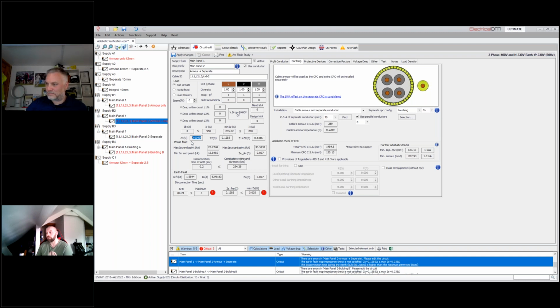And when you increase the size of your phase conductor, overall, you're reducing your overall impedance as an earth path effectively. So you can reduce this number more effectively by increasing the size of your phase conductor rather than trying to throw more copper at it in parallel. But it all comes down to the size, the number of conductors. Is it more cost effective? Is it going to cost you more to get groundwork and duct work down in there and then bury all that in?